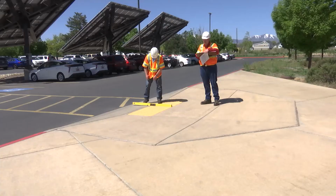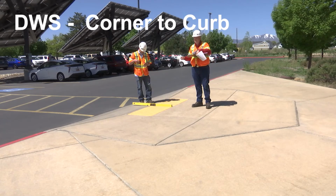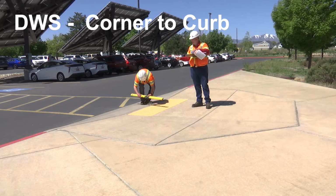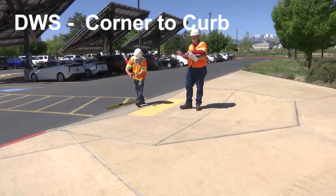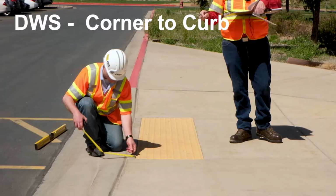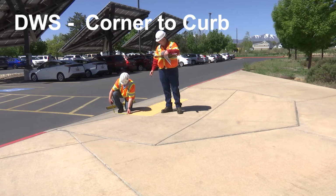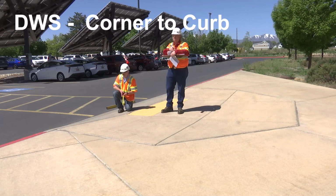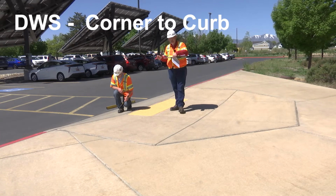We've verified it's 2 feet. Next, we make sure that we have 2 inches from the detectable warning surface to the top back of curb, and our detectable warning surface has to be within 2 inches of the base of the curb cut. So first, within 2 inches of the top back of curb. Here we have 4 inches, so we are greater than 2, so we're just a little bit too far away.